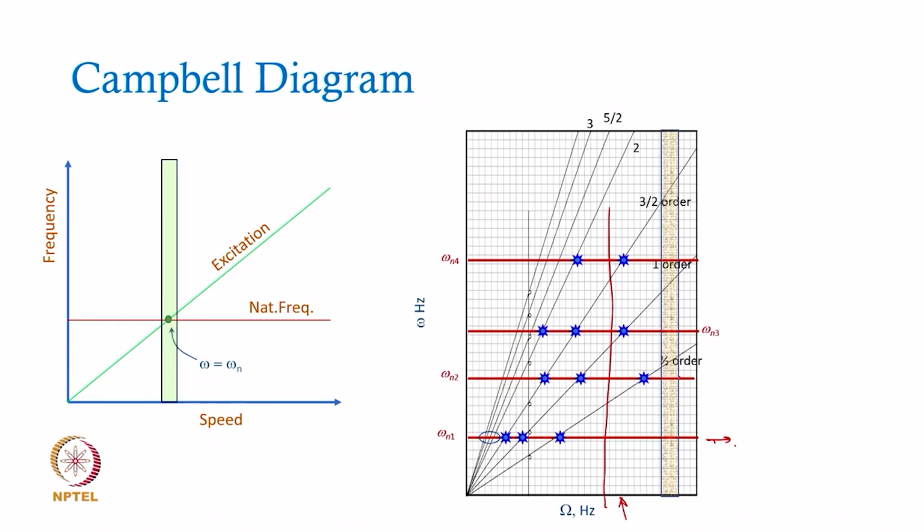I have not animated it here, but I may shift these lines if possible the other way. In the base excitation case, either you increase the speed of the vehicle or you change the suspension for the same speed. So, either you change your operating condition or you change your system parameters, that is what you have. And I mean, this looks good on paper, but in reality both of them are difficult, okay.